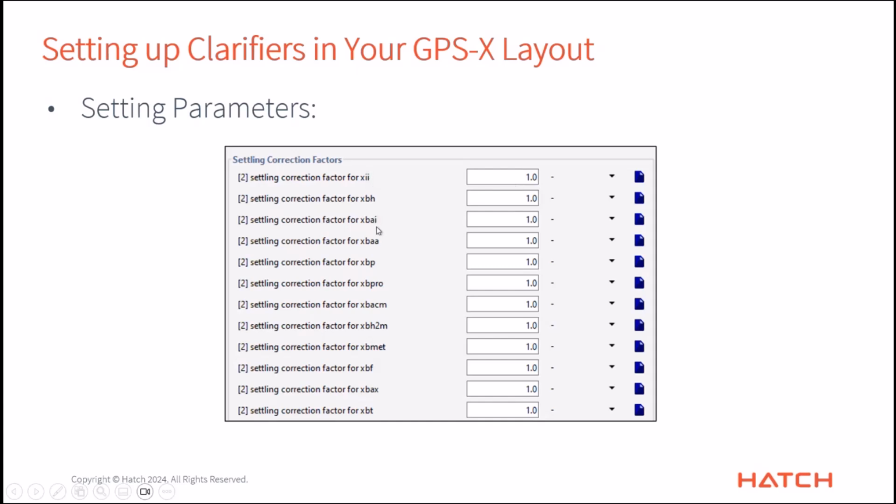So these next few parameters here are the different biomass types. So maybe it is kind of a thing that the Anammox biomass is really good settling. That's this one down here, XBAX. You could come in here and change that, because it's a granule kind of thing, and it is going to be settling better than the others.